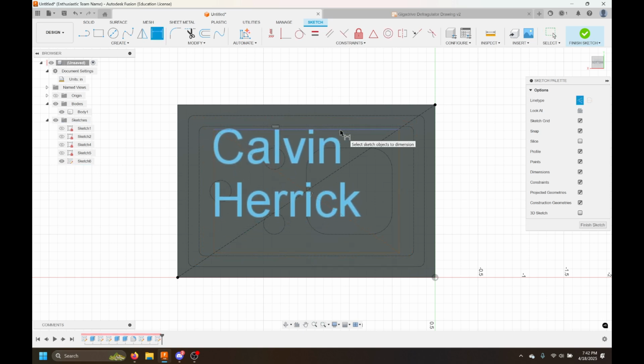So I'm just gonna drop down some dimensions. The hotkey for dimension is D, also a nice one. Drop down a dimension right here. It doesn't really matter what these dimensions are, because the size of the text box doesn't change much. I think you might have to have it be bigger than the text. That might be a thing. But if I put dimensions on both of them, no matter what they are, they're gonna be random numbers, it'll be constrained.